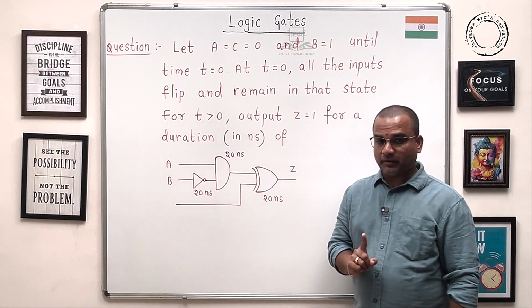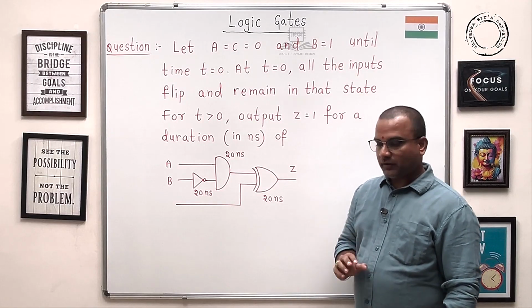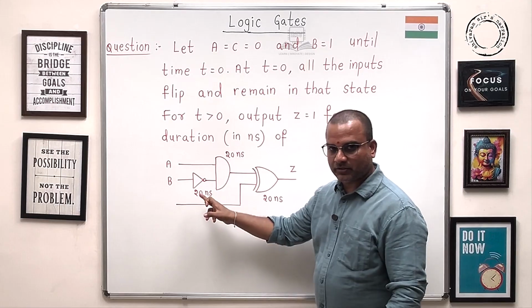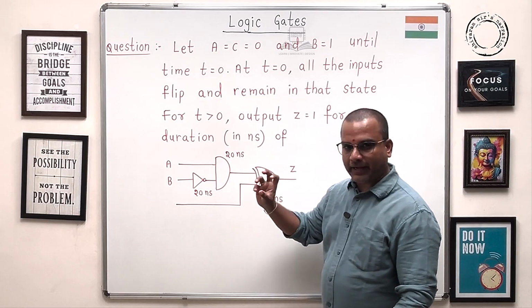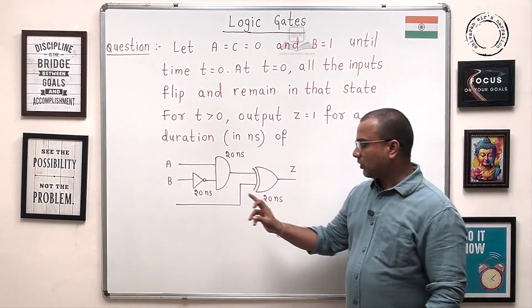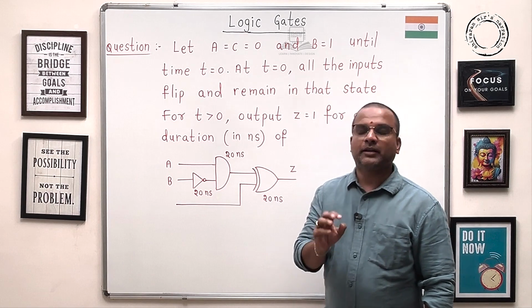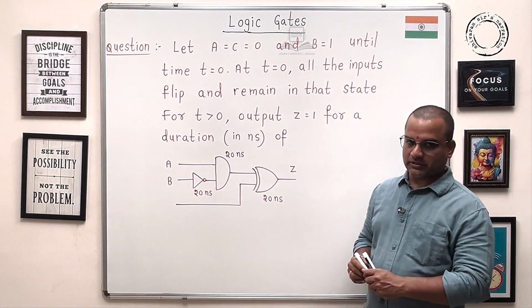Actually guys, remember, in these kinds of design challenges, wherever near the logic gates, if they give some time period, it is a propagation delay. So all the logic gates have identical propagation delay, that is 20 nanoseconds.